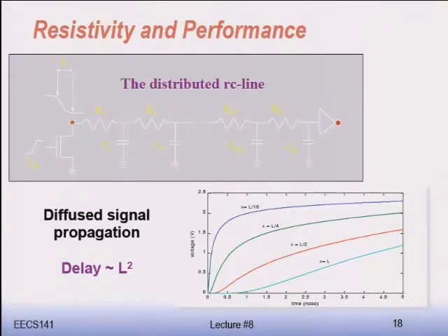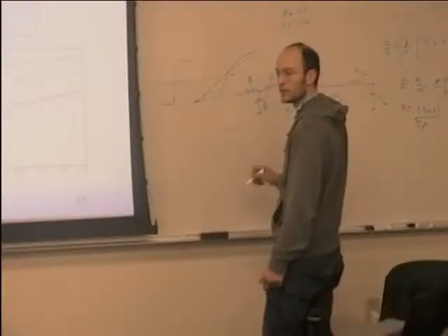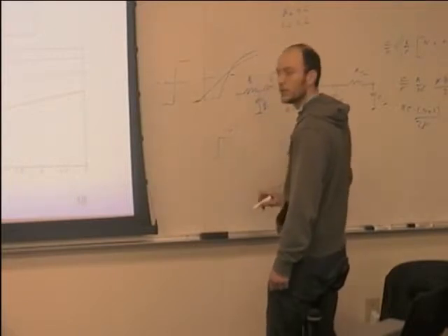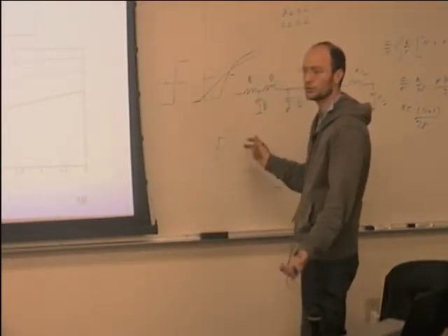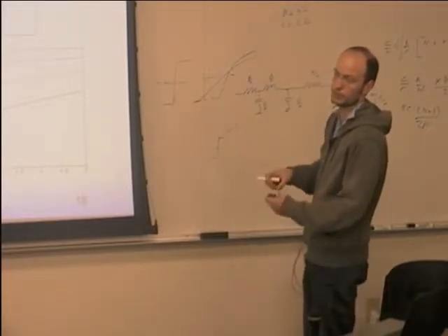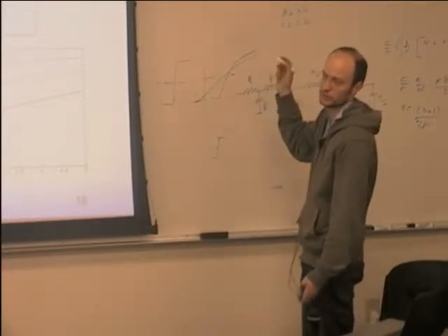And so as you go from left to right, as I was saying, not only is there a delay, but also the signal becomes slower and slower, right? So in other words, I can tell you that the delay is 10 nanoseconds, okay? And the input is a step. If I told you only these two things, you can't draw the waveform at the output, okay?